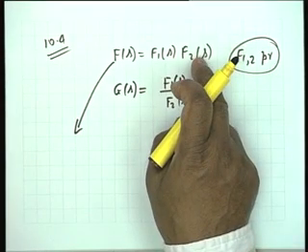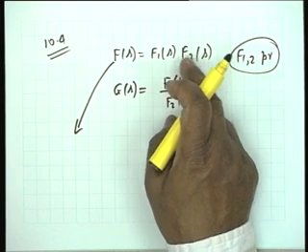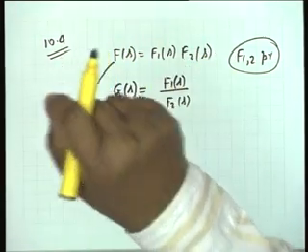Here you don't have to go to the j omega axis, because nothing is known about f1 and f2. You don't know whether they have poles on the j omega axis. Well, we know that if they have poles on the j omega axis, they are simple. But these two poles may be coincident. F1 of s may have a j omega axis pole at the same point as f2 of s. Then they will have a multiple pole at s equal to j omega. So this is one reason.